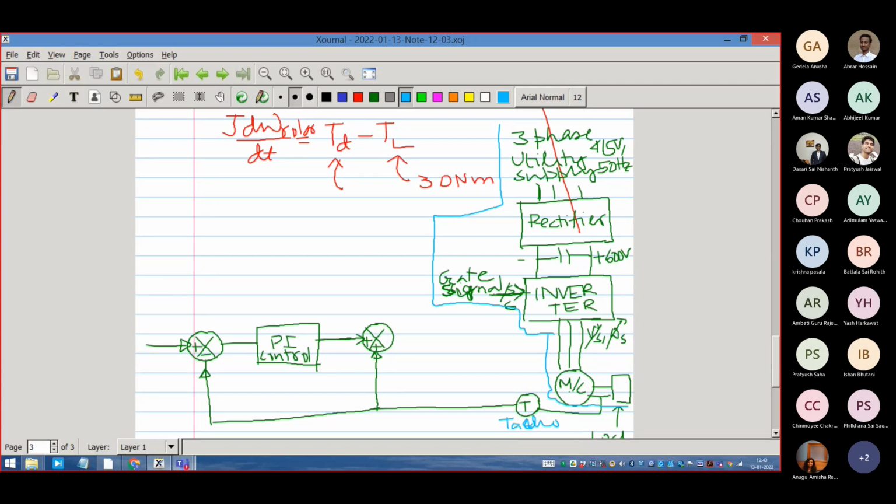It can be a microcontroller. The analog signal will be converted to digital through an analog to digital converter, and then it is in the digital domain. This is in the control domain, where the signals have no strength and their voltage levels do not matter. In the digital level everything is a code, operating only on digital logic of high and low. So a PI controller is also written in the digital domain. It is a code. Integration can be written in terms of a code, multiplication can be written in terms of a code, right?